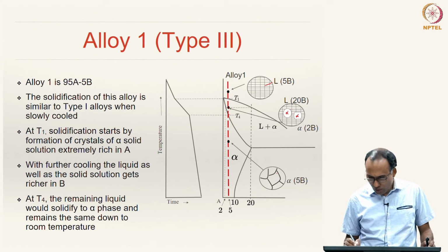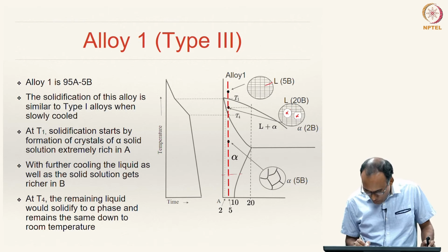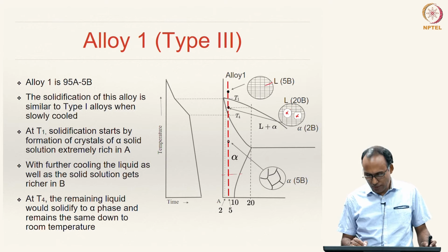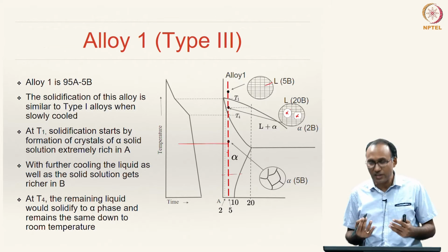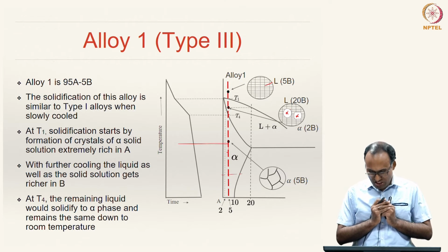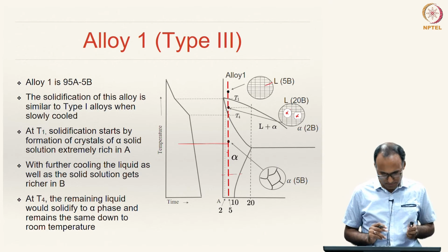As you are coming down, all that happens is the alloy composition is phi b, but everywhere the solubility at each and every temperature is much larger. So, it is actually not saturated, it is undersaturated, and hence nothing will happen. The alpha simply, as you are cooling down, reduces its sensible heat. Basically the temperature of the solid reduces, nothing else happens as far as the microstructure change is concerned. Alright. So, it is very similar to our isomorphous alloy system.